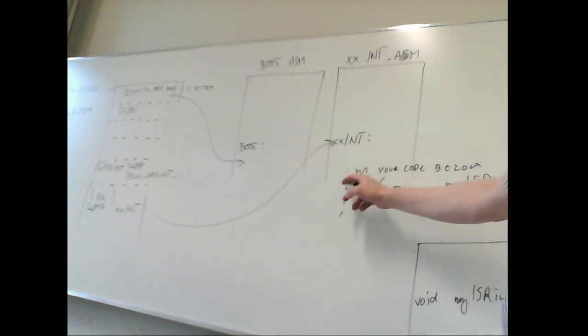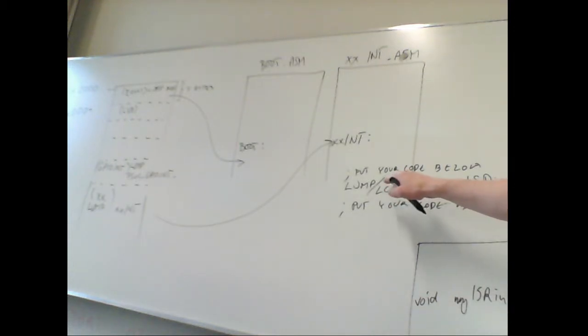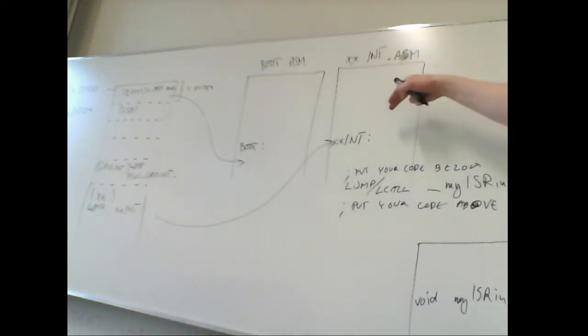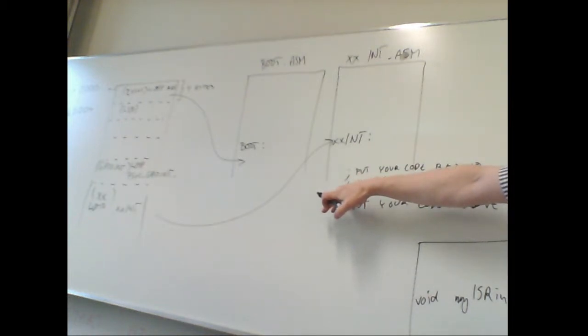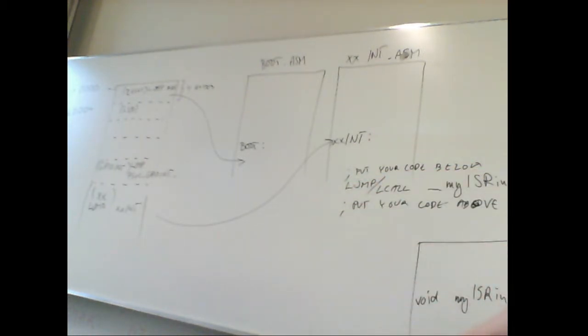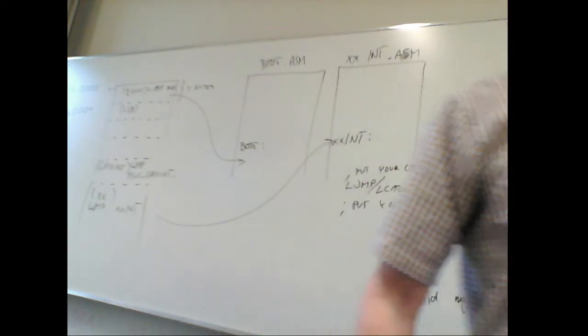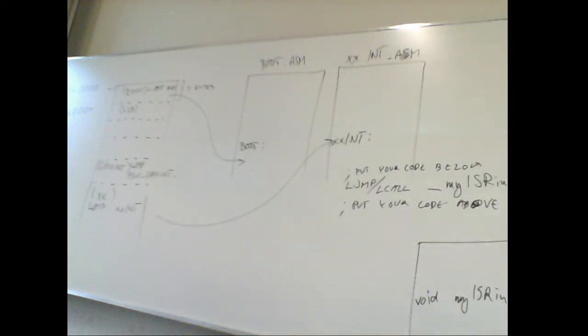The difference between long jump and long call is that if it's a long call, then this routine here is a normal function, nothing fancy about it. However, you can also do a little bit faster code, not much, a little bit, by not returning here at all. But in here, you do a return from interrupt instead of return. Okay, I should probably use another color here.